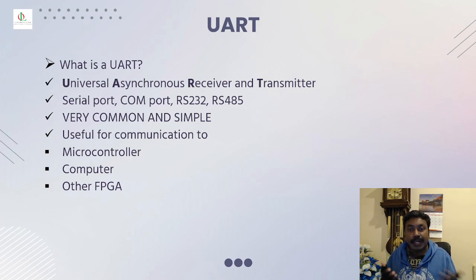So likewise, UART can be used in all those useful communications, and UART has also been called by other names. For example, you will hear people in the industry call it serial port, COM port, RS232 port or RS485 port.